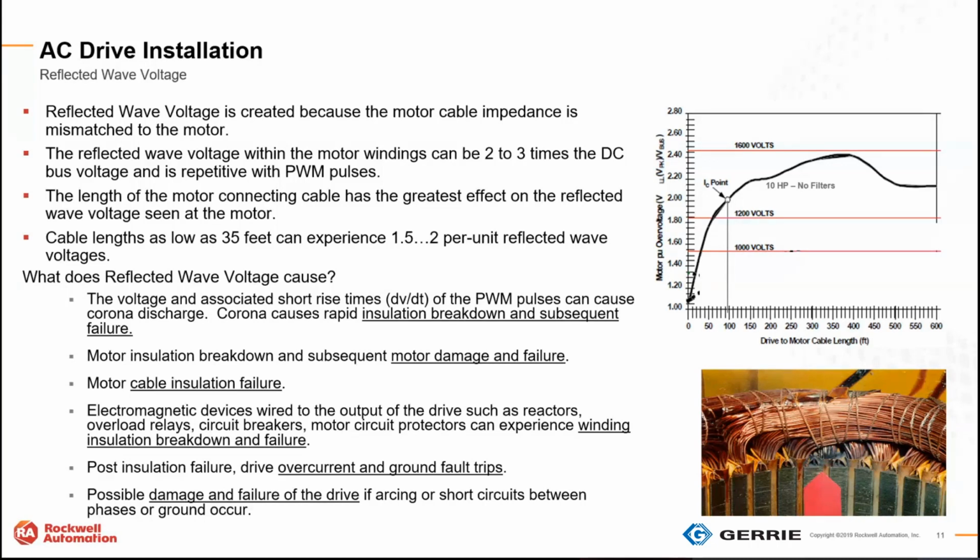And sometimes, in some cases, we've actually seen the cable supplying the motor, or the cable going into the pecker head of the motor, start to fail at that point. So even before the motor failed, the cable actually started to fail. So again, it's usually something happening out at the motor. The cables will fail close to the motor as well.